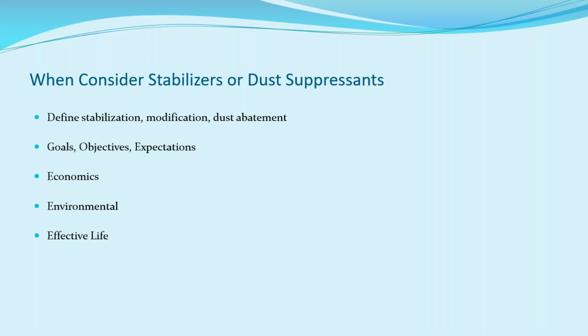And how are you going to say, oh, well, the asphalt was bad? Well, you can't do that because you can't test it. So take a sample of it. The Ohio State DOT has sampling and testing procedures. Use those testing procedures and sample whatever you buy, so you can make sure you're getting the product that you're supposed to be getting.